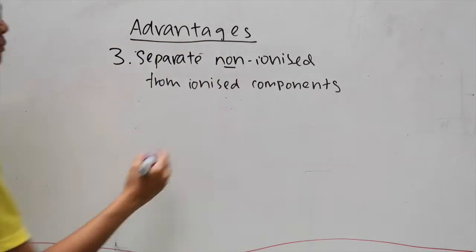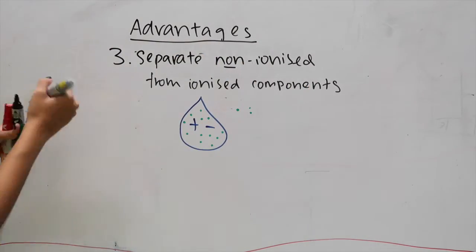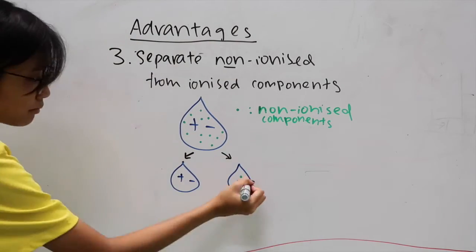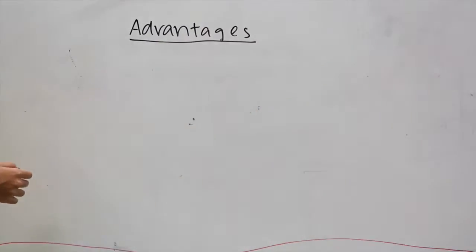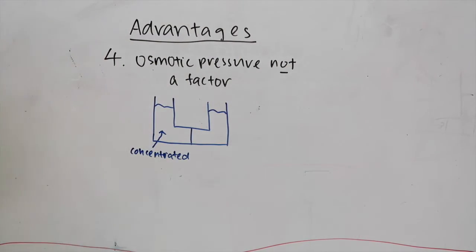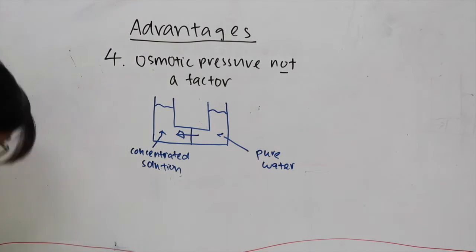Thirdly, as ED system removes only ionized species, it is particularly suitable for separating non-ionized from ionized components. Lastly, osmotic pressure is not a factor, thus the pressure can be used for concentrating salt solutions to 20% or higher.